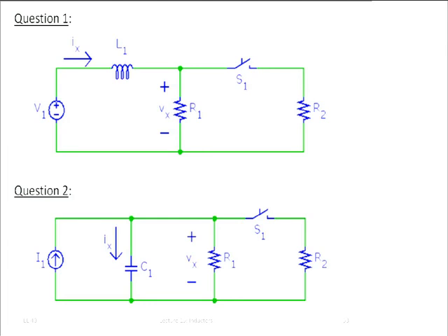If it's a second-order circuit, you will get the first-order derivative and the second-order derivative. It's exactly the same nomenclature as you used in math, right? In math also you had first-order linear differential equations, second-order linear differential equations, then just linear differential equations and probably Euler equations and so on. We will get second order if there are both inductors and capacitors. Even if you just have capacitors but multiple ones, you can make second-order systems. If you separate the capacitors with resistors, you get that. Okay?